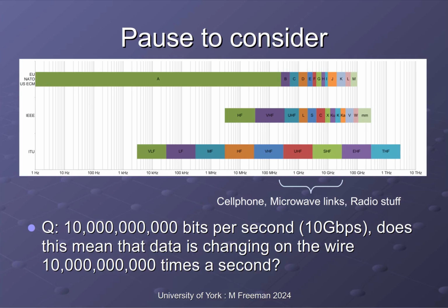If you look at the frequency range for radio frequencies, we'd have a hard time persuading those bits to stay within the wire, because obviously once you get up into the gigahertz kind of region, you're in the land of UHF, ultra high frequency transmissions. So your copper wires will start to act like antennas. So what we typically find is that we need to reduce the frequency components that we use to transmit our data. In general, copper wire does not like high frequencies because you'll find that the natural resistance, inductance and capacitance associated with your cable will start to attenuate those higher frequencies.